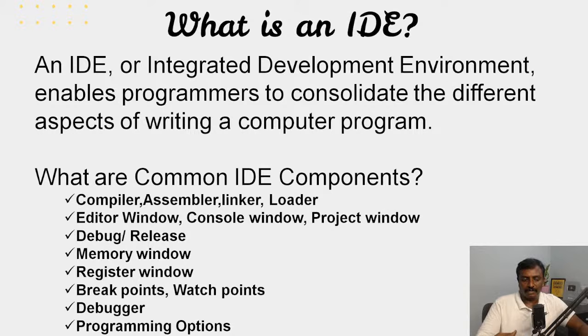And then you have the programming options. Sometimes, you need a flash programmer. For example, for Keil, you need Flash Magic or Nuvoton software. The manufacturer will give the flash programmer. Sometimes the programmer will be inbuilt. If you take Xilinx Platform Studio, they have the programming options inbuilt. Whereas for Keil, you need separate software for programming, like Flash Magic or Nuvoton. That depends upon what kind of manufacturer you choose.